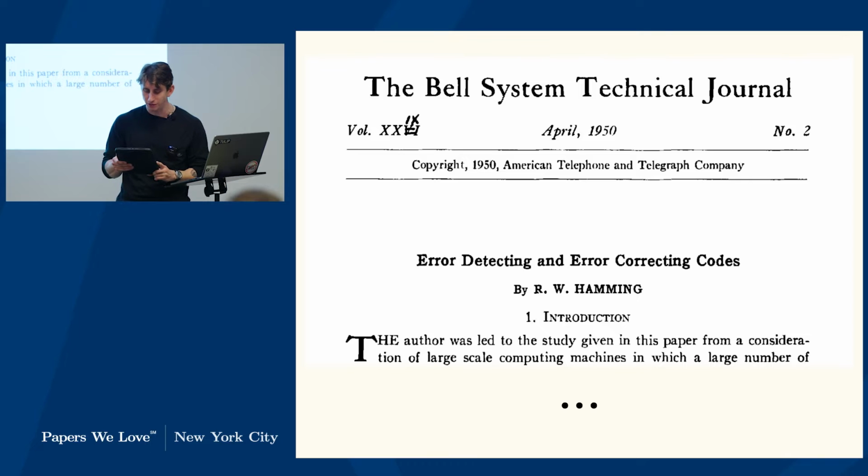"In a telephone central office, for example, a very large number of operations are performed while the errors leading to wrong numbers are kept well under control, though they have not been completely eliminated. This has been achieved in part through the use of self-checking circuits. The occasional failures that escape routine checking are still detected by the customer and will, if they persist, result in customer complaint. Well, if it is transient, it will produce only occasional wrong numbers. At the same time, the rest of the central office functions satisfactorily."